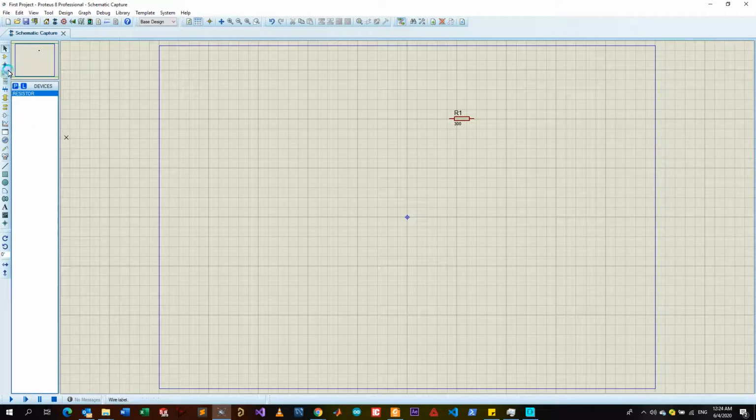So as I go down, as I was explaining, this is the sub-circuit mode. You can add your inputs, your outputs, your power. You can get your signals. If you want to get a DC signal, a sine wave, a pulse wave, if you want to generate any signal, you can get it from S. If you want to add any probe, if you want to measure voltage, you just go here with this one, then you go and you click on the resistor.